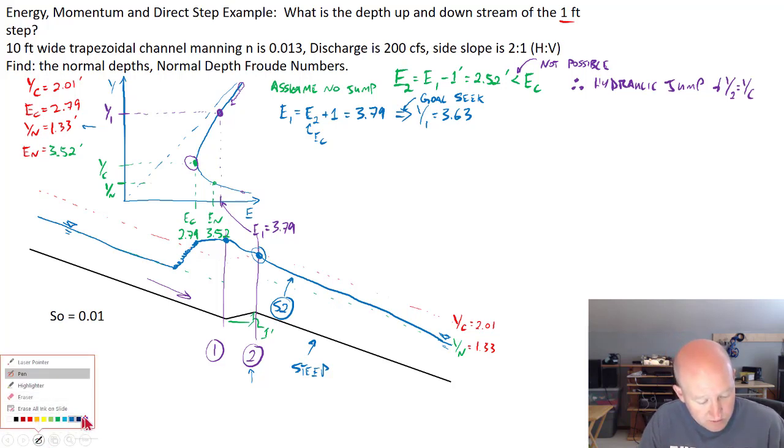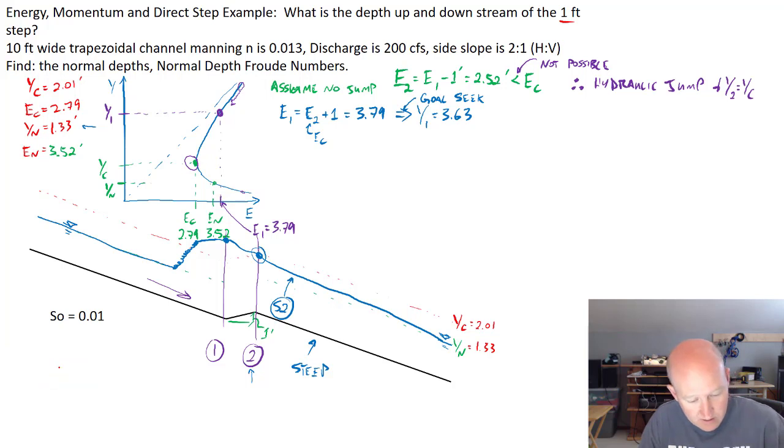We're going to use our specific force concepts for that. So we're going to go from this side of the jump to this side of the jump. And we went through that example previously. This is the idea that if we look at impulse momentum, this idea of a jet striking a plate, what's the force on the plate? That the forces of the water on the inflow and the outflow are going to balance out. Otherwise, this hydraulic jump would be moving.